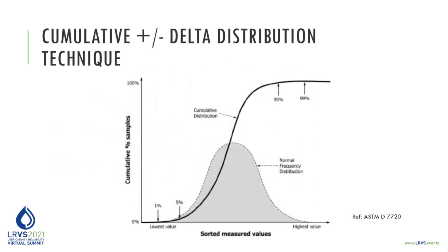Now here's an example of the cumulative distribution technique. An example here is a data set having some normal frequency distribution with a bell-shaped curve and two tails and so forth. Now viscosity measurements often fit this form. The shearing of viscosity improvers, typically that's what happens when you shear down the viscosity, is the viscosity improvers are actually shearing down. Those polymers, typically polymethylmethacrylate polymers, they shear down, thins out the oil. You can also get fuel dilution, contamination, that can occur as well with engine oils. That causes viscosity to decrease. We can also go oxidation and soot accumulation can increase viscosity.